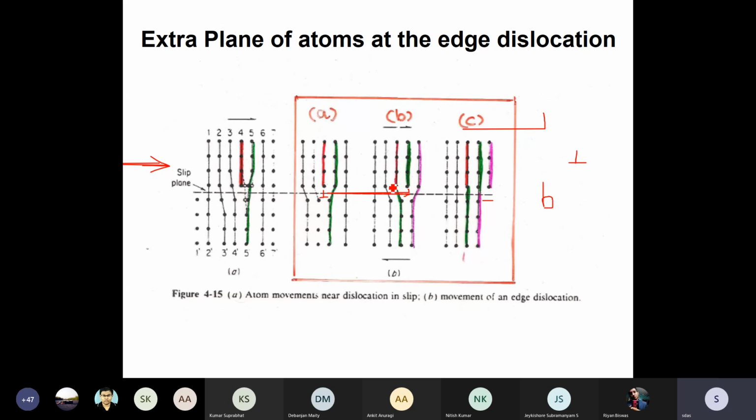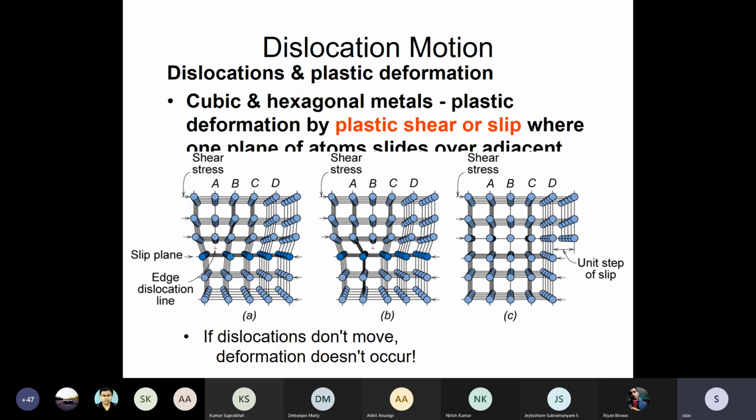This is how an edge dislocation moves. The same thing, another picture: the ball and stick model appears to be 3D. It snaps away this bottom portion, and eventually it reaches the surface. So one plane at a time, you snap the plane, break one bond, and create an offset, and the magnitude of this offset is the same as the Burgers vector of this dislocation. Any question?